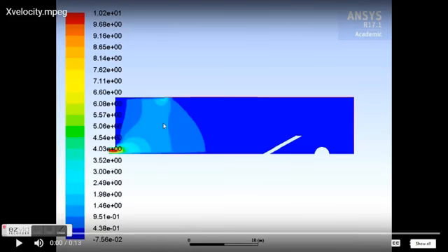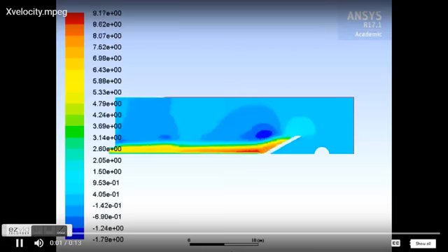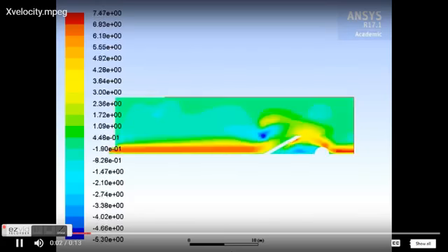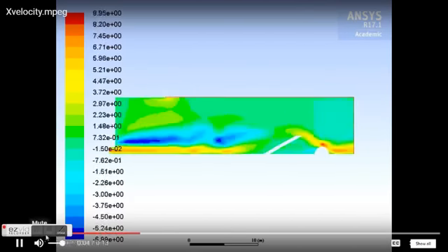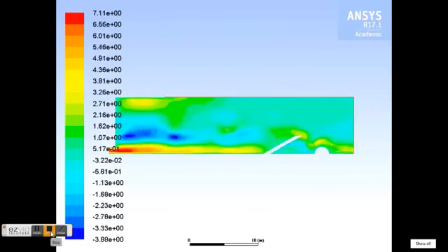The following is the u velocity plot of the same solution. Note that the low velocity forms at the ramp base where the jump occurs and increases past the weir, where it accelerates again.